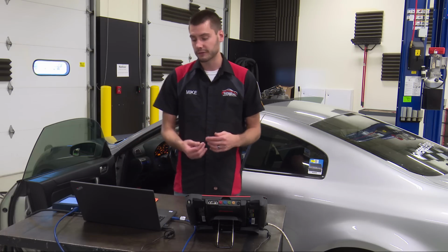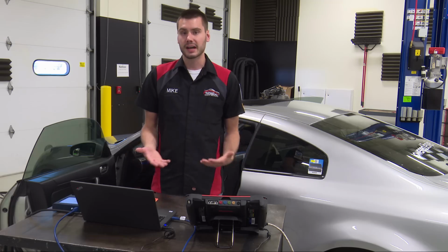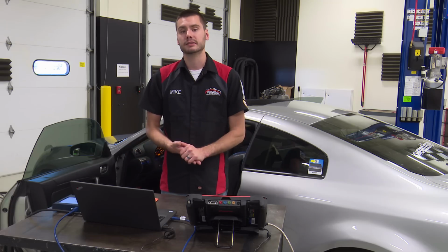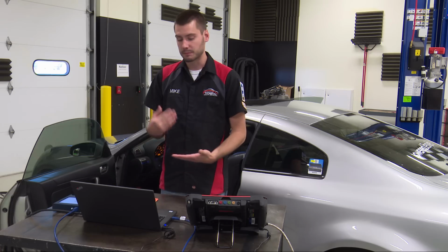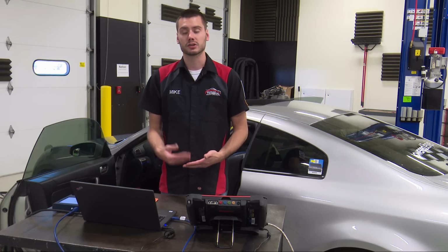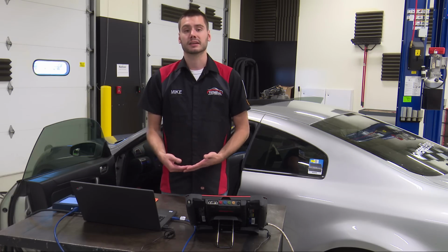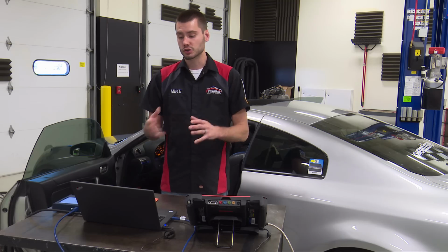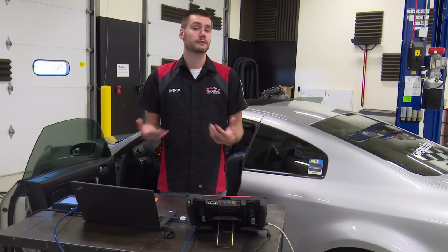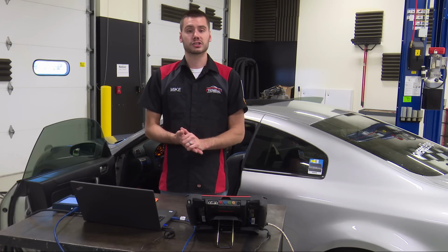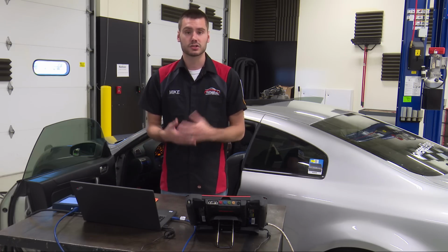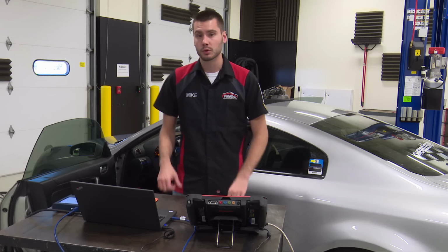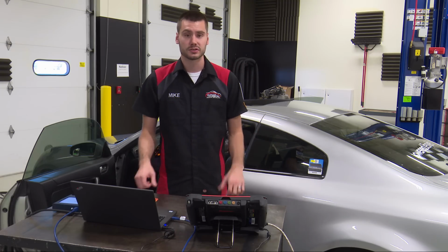Now, would this motor affect an older style switch? Probably not nearly as much, but we know we have a computerized circuit that doesn't like noise like this, and it doesn't like the excessive current, especially on the downward swing of this motor. So we do have an issue with this motor. Now, unfortunately, our customer here has chosen not to fix this car. He's chosen not to replace the window motor on the passenger side.